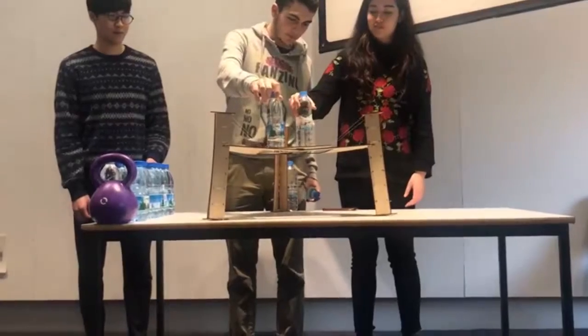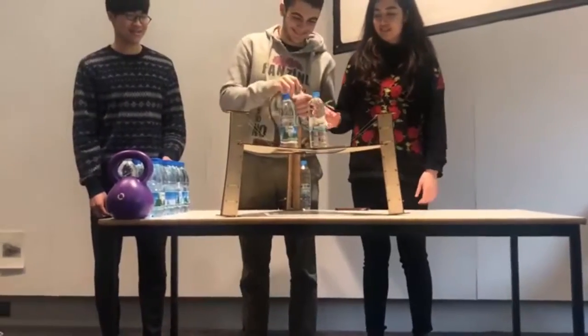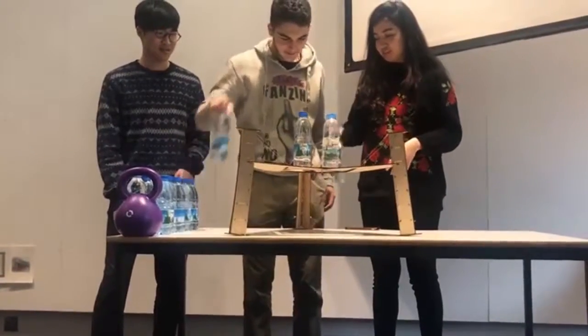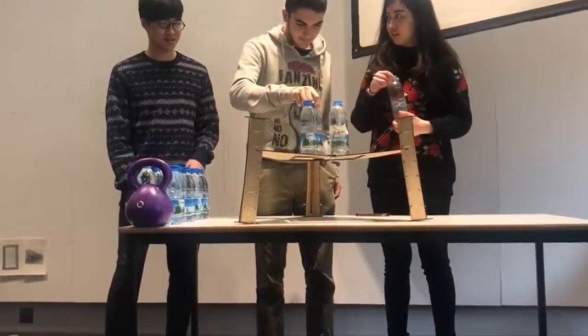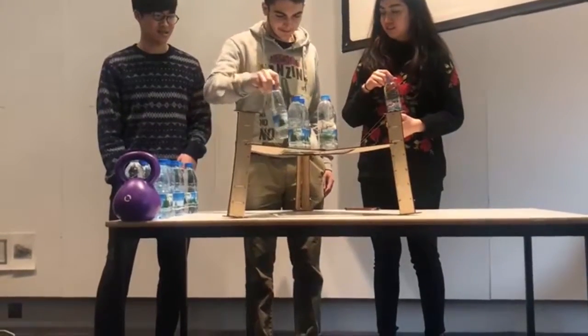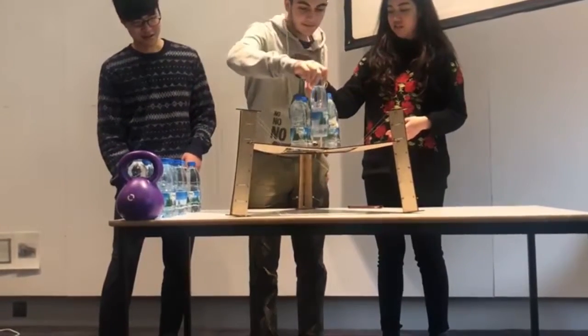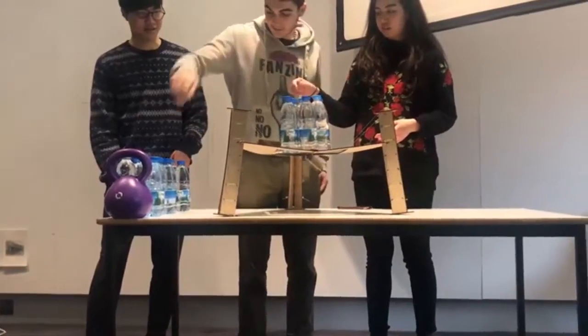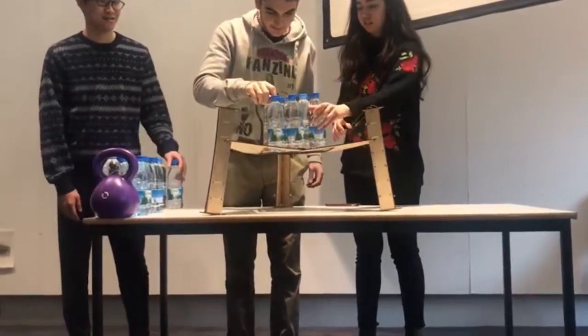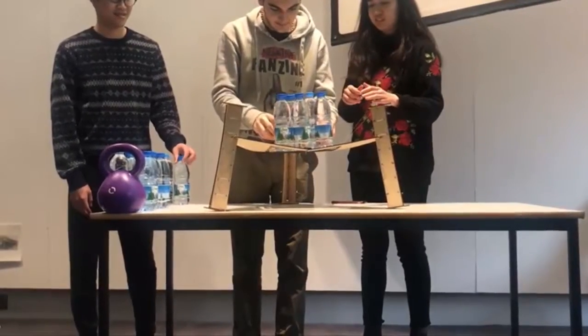As the weight is being applied, the loading platform immediately glues to the lower platform. The strings are working in tension, while the loading platform is compressing the lower platform as the weight is being applied. As the weight continues to increase, the lower platform starts to deflect, causing the column trusses to lean towards the center.